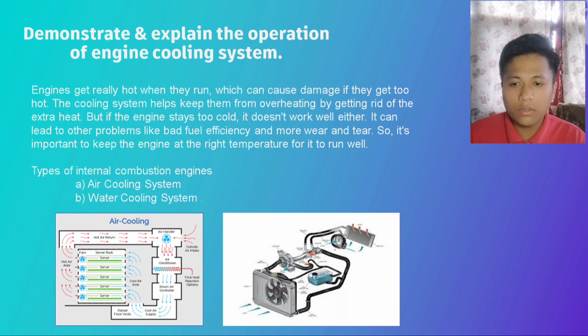However, the cylinder wall must not get hotter than about 500 degrees Fahrenheit or 260 degrees Celsius. Higher temperature causes lubricating oil to break down and lose its lubricating ability. Other engine parts are also damaged. To prevent overheating, the cooling system removes the excess heat.